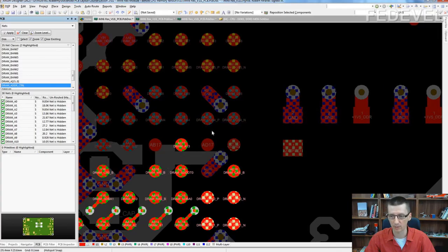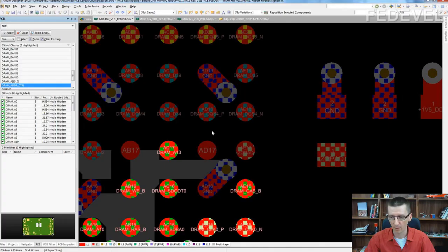So start with differential pair signals. Before I actually click there, we need to set something because we have not been using differential pairs yet. We need to set up a rule which will specify how default differential pair will be routed. What will be the thickness of the track and what will be the gap between two differential pair tracks.